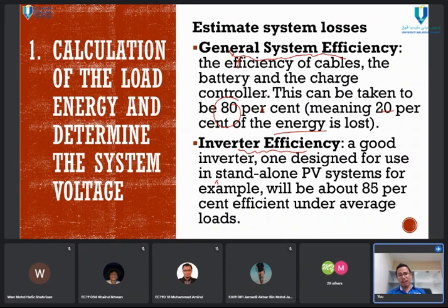Seriously, if you wrongly choose that, you are going to struggle when your system always shuts down, because it is actually coming from the inverter. The AC load is quite heavy, plus the inverter efficiency is poor. Originally maybe only 5 amps, it can double up or triple up your current consumed only because the inverter is not appropriate.